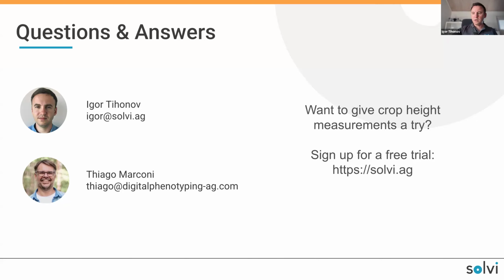Hmm. I think it's not critical to be the exact same altitude. Both in the range, I think I mentioned in one of the slides, what we've seen works best is somewhere between 30 to 50 meters. It doesn't have to be low. And actually, I think there was another question about why you shouldn't fly low, so I wanted to clarify. Flying low above tall crops is when usually you will have problems. For example, a typical corn trial with corn plants being 2 or 3 meters tall.